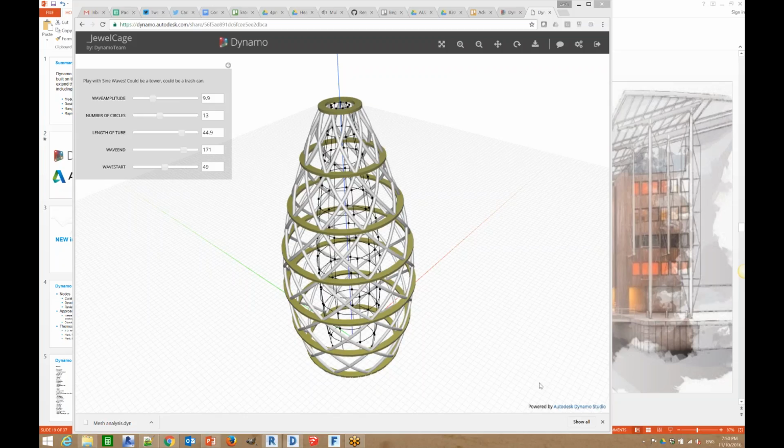And the logic would be something like: find the center point of all of my panels and find the solid volume of my room, and for each panel give me the room that it is closest to, which is essentially what they're doing with the MEP workflows.